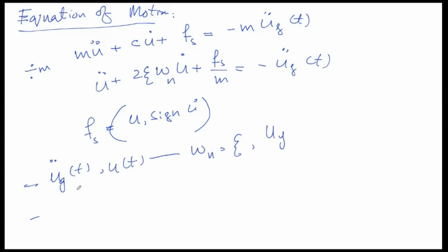While for the same ug, the ductility factor depends on omega n, it depends on the damping, as well as it depends on the strength reduction factor.